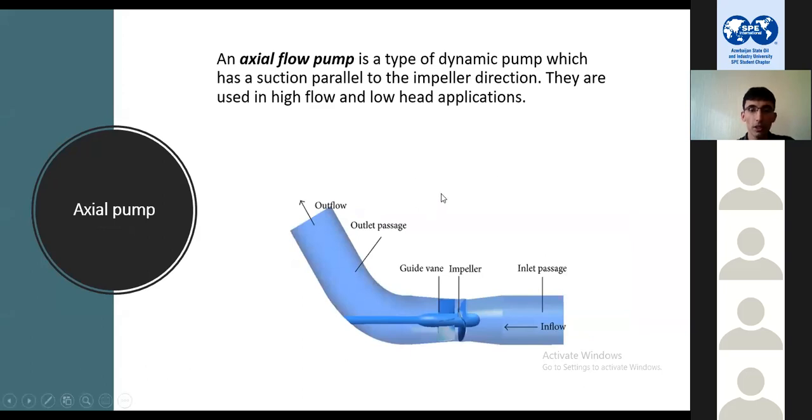Yeah, the axial pump. You remembered it. In our loop reactors, we had some axial pumps. It's called axial because the inlet and the outlet direction of the fluid through this pump are on the same axis. It's not perpendicular to each other as it was in the centrifugal pump. So it's called an axial flow pump. This pump is not actually used to create higher pressure, because it cannot.